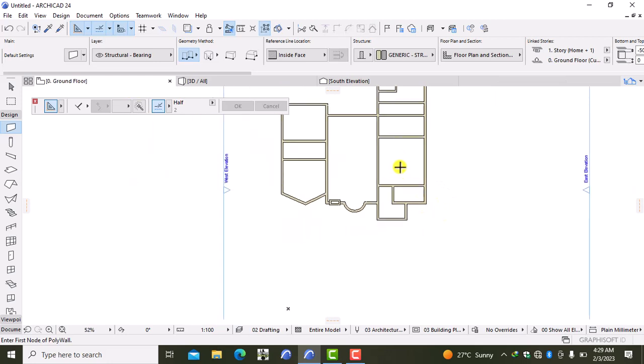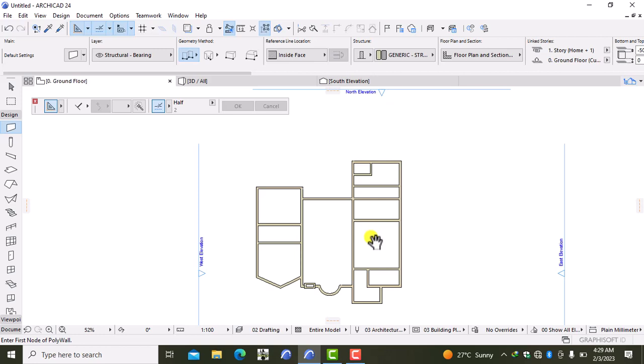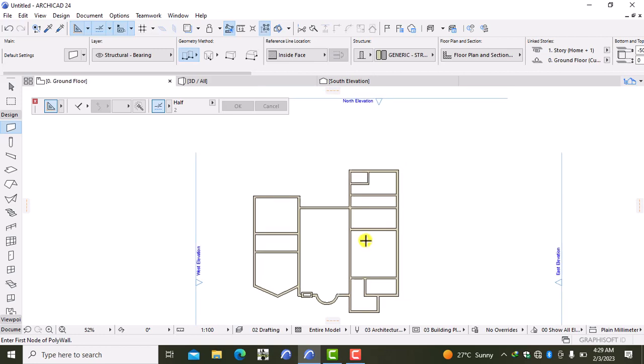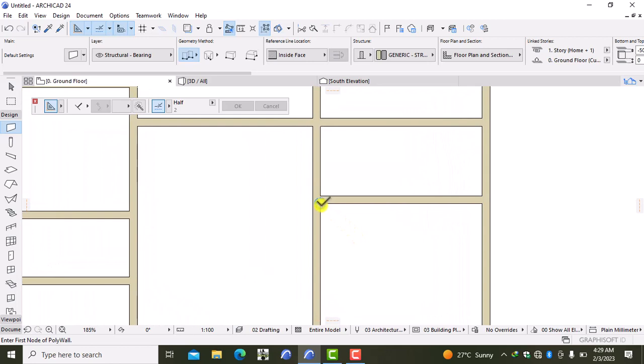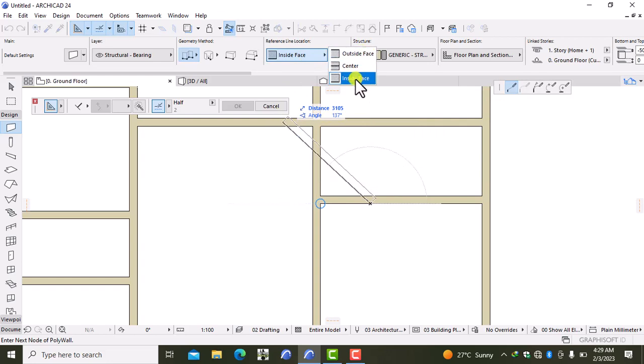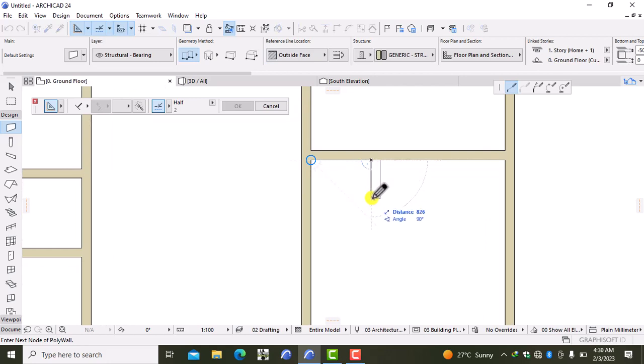So basically with this, I'm done with the orientation of these particular walls. Only one thing remains over here, I need to do another wall from here at a distance of 1200. Distance of 1200. So basically for accessibility of our house and the corridor, you can decide to do a corridor of maybe 1 meter, but I like to use 1200, so that you don't end up using a very huge corridor that's occupying a lot of space of your house. So you should try to minimize on that. I'm just going to drag it to the distance of 1000. Enter.